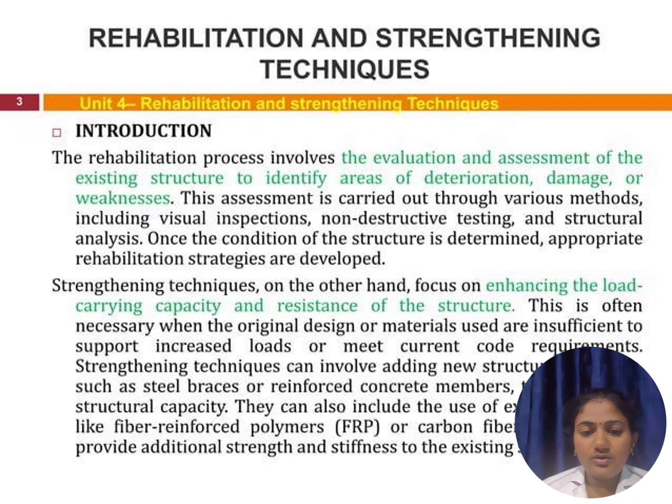And while coming to this unit, we have an intro. Rehabilitation includes evaluation and assessment of the existing structure to identify the damage or weakness that is attained in the structure itself. And strengthening focuses on increasing the load carrying capacity and resistance of the structure, and by using steel braces or reinforced concrete members, we are making it stronger when compared to the previous one.